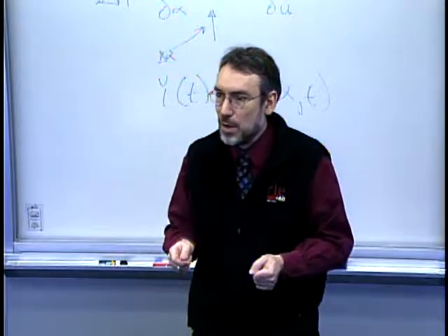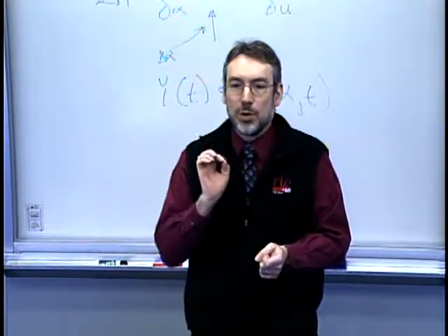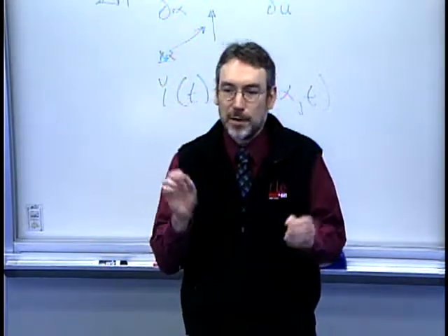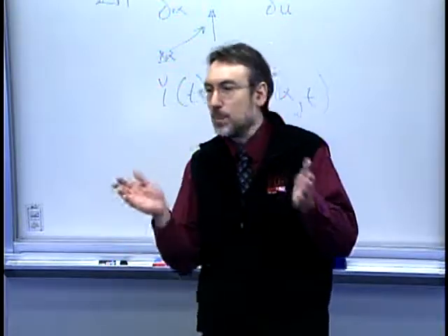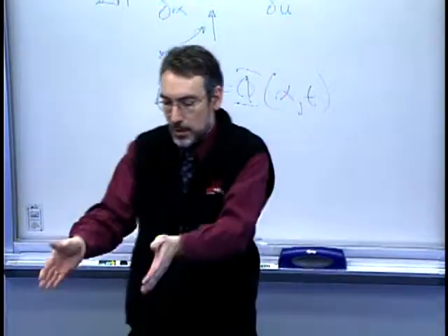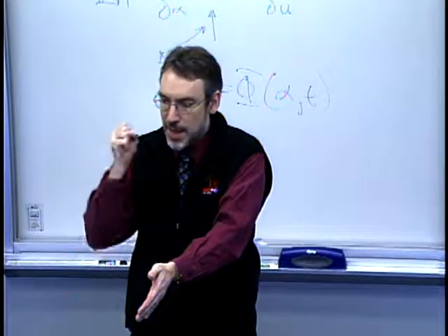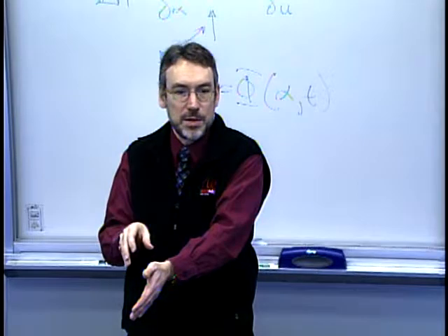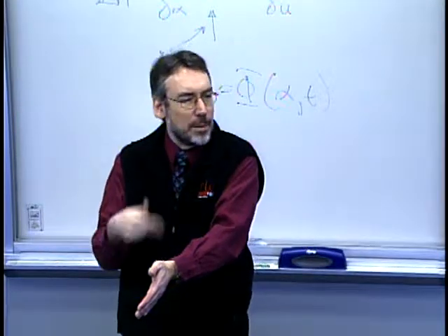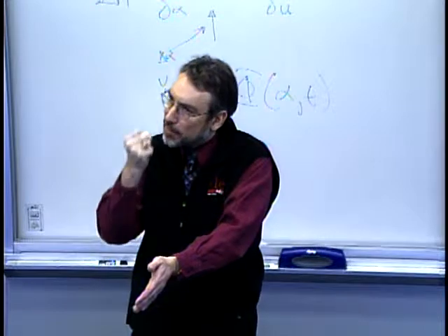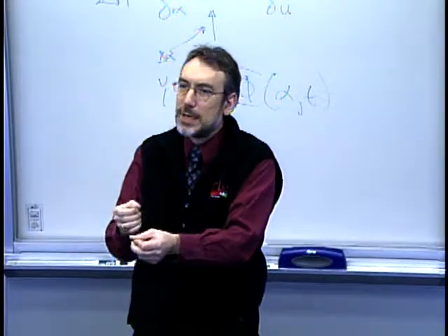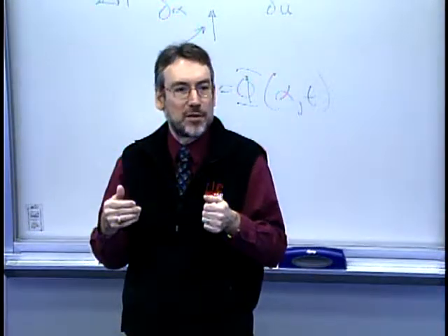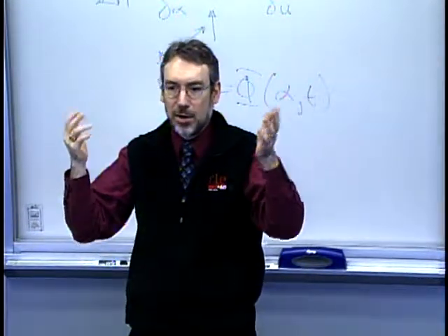So for example, there's a reproducibility and there's a repeatability component to typical gauge studies. One component, just real quickly, would be I've loaded the part on the measurement apparatus, and then I just fire whatever the measurement sequence is multiple times. You can think of that as a pure repeatability. Somehow, kind of the physical, maybe it's an optical measurement. There's scatter from extraneous light sources nearby off of that.